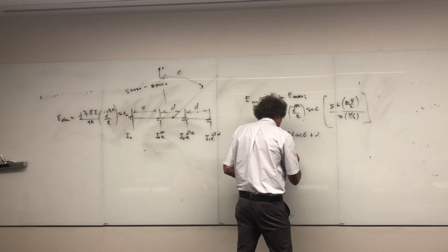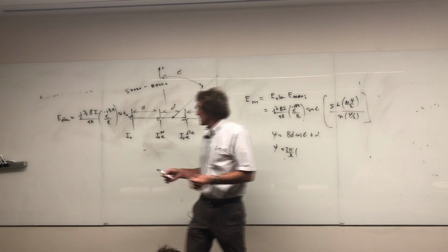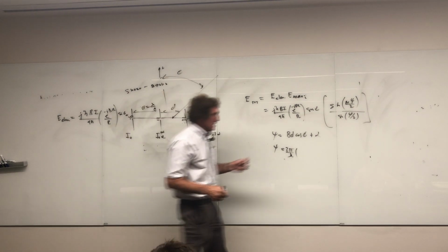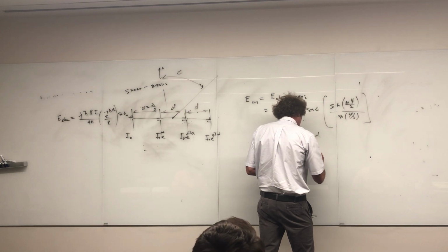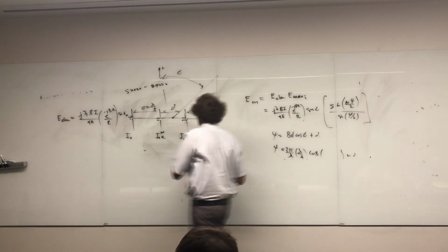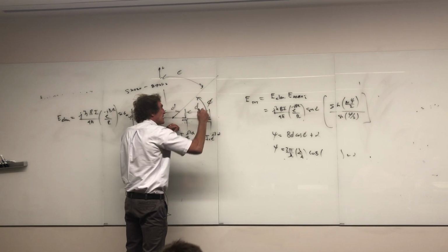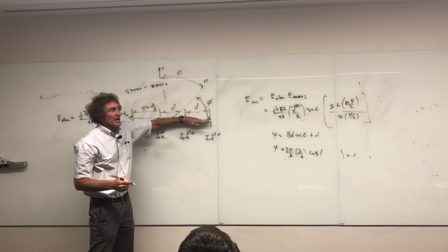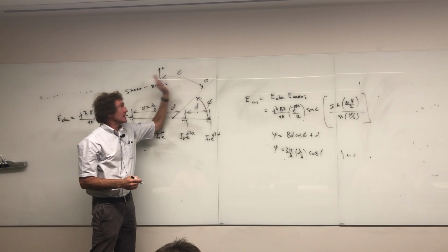And d oftentimes is in terms of fractions of lambda. Usually, if you set the spacing here, if d was equal to lambda over 4, as an example, then d here would be lambda over 4 cosine, plus alpha. Now you'll notice that this angle, when I talk about cosine alpha, alpha is phi, the angle that the radius vector r makes with respect to the array. Because we're shooting out at this angle, right? We're at a distance r away at this angle.